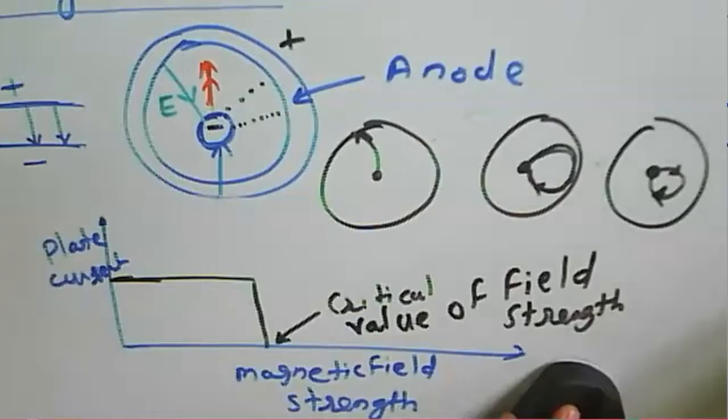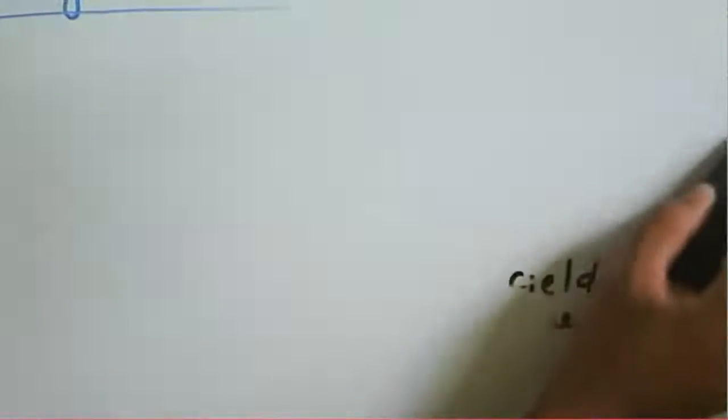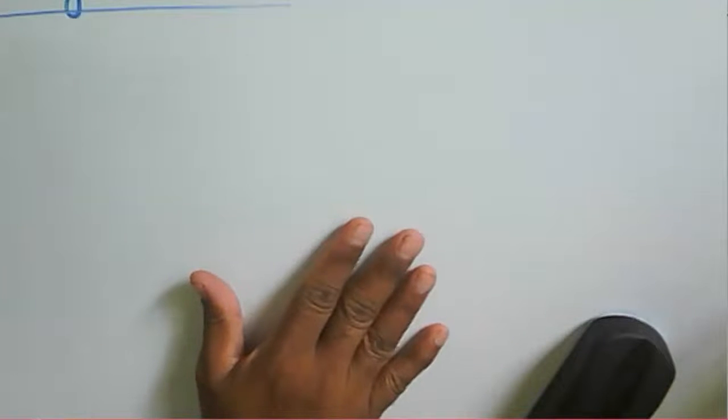Okay, it is opposite here. Now in a magnetron, instead of a plain anode, directly the anode has some cavities. So the anode structure in a magnetron is just like a cavity one. There are various types of magnetron.